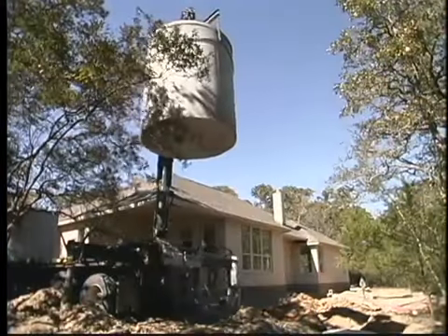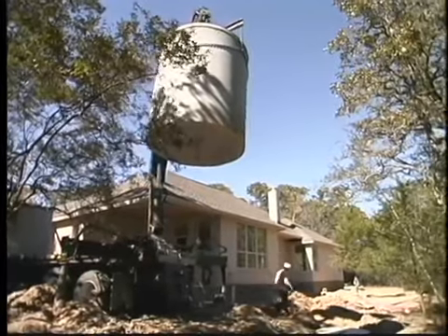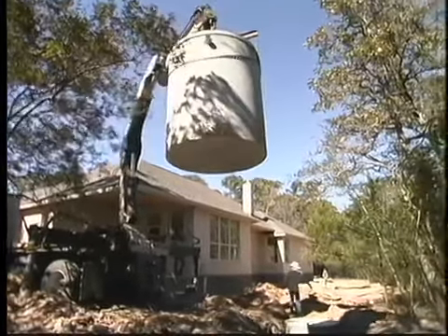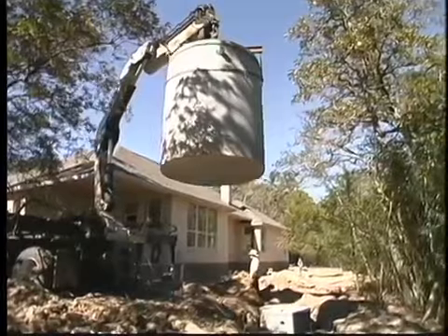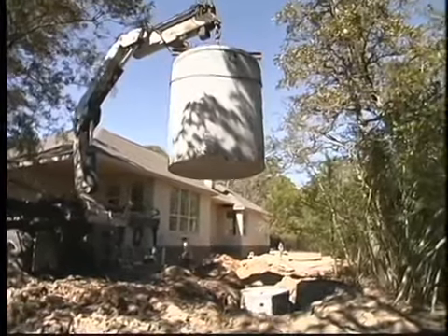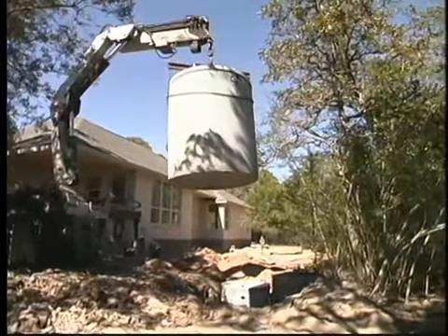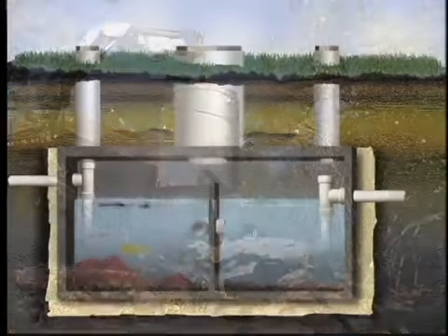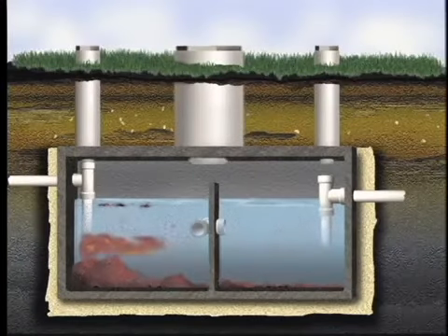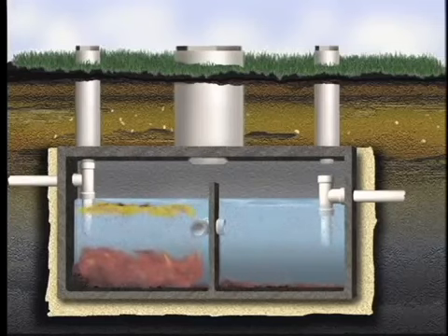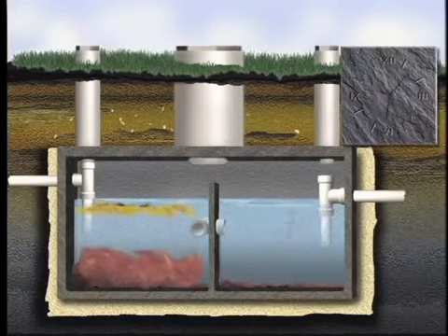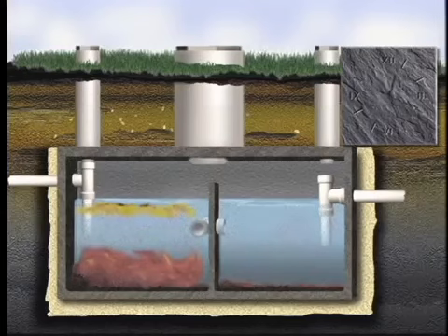A septic tank is an enclosed watertight container consisting of one or two compartments. It collects wastewater and provides primary treatment by allowing floatable and settleable solids to separate from the water. Settleable solids accumulate at the bottom of the tank, while floatables, such as oils and greases, rise to the top. Water should remain in the tank for at least 24 to 36 hours to provide optimal treatment.